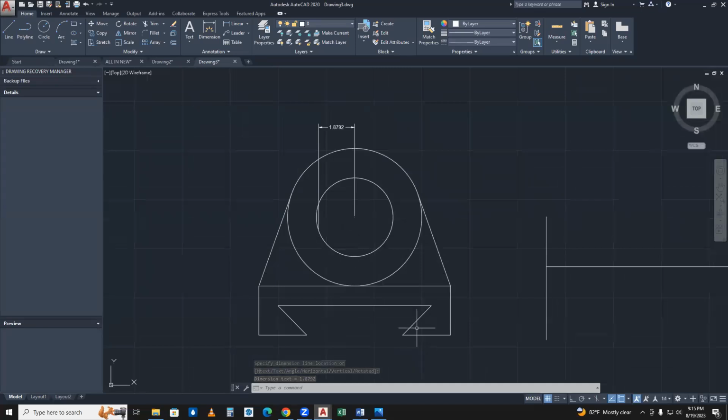And if you're going to show the diameter, we are going to show it on the circumference. So you will put an arrow to the circumference and then put the diameter. So there are different methods, right? Both are correct. So depending on the requirement and the standards, we should go with that. Fine.